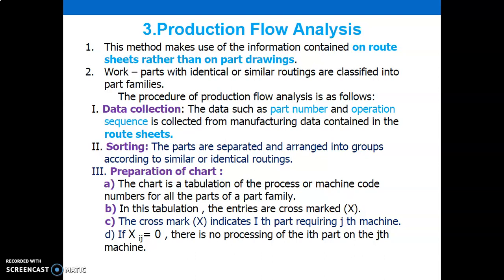Now moving to the third method of group technology. This method makes use of information contained on a route sheet rather than on part drawing. Work parts with identical or similar routing are classified into part families. The procedure of production flow analysis follows.